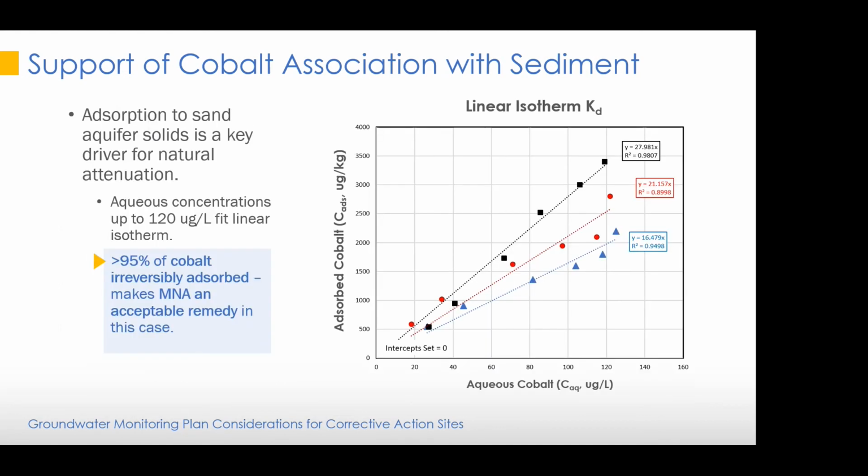So we're starting to identify a mechanism of what's driving the suspended sediment issue. Now you can go one step further and keep diving down. And now we're starting to look at what this adsorptive process is. And so here we're looking at a series of tests that were run to develop linear isotherms, or KDs, for the cobalt on the sediment in this particular site.